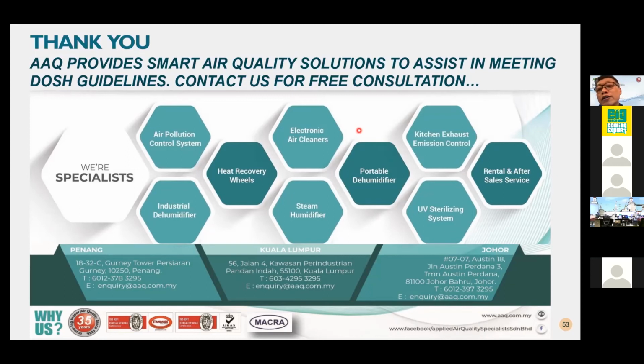If you're installing the UV in the AHU and using an electronic air cleaner, like I proposed, the filter frame is all metal, aluminium, so you won't have this degrading issue. With MERV 14 and UVGI, you're able to get 97, 99% efficiency, as the table shows.